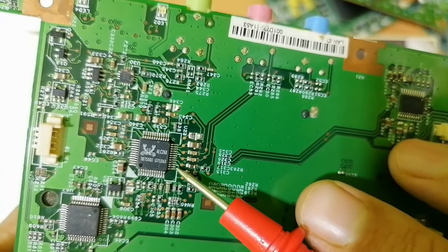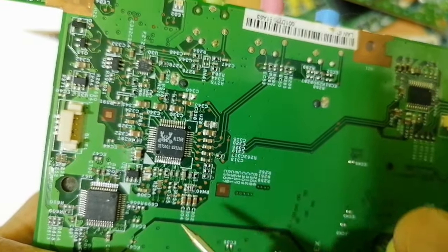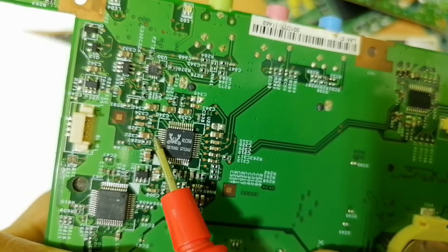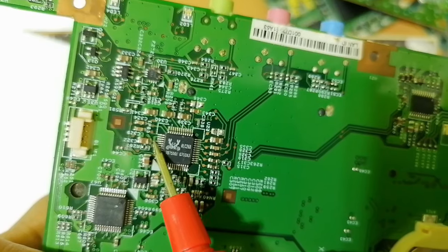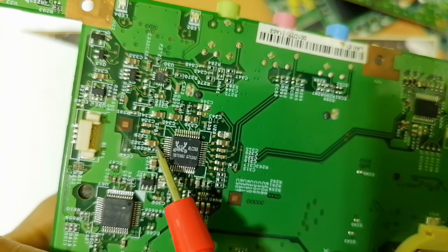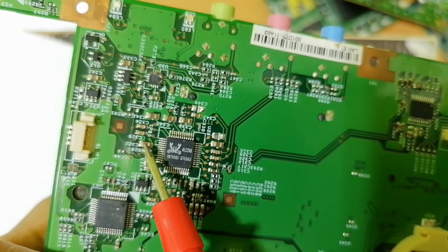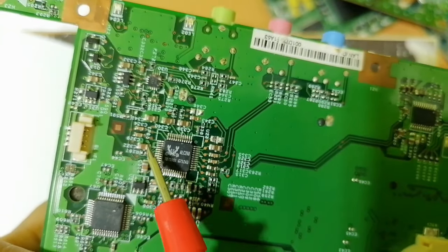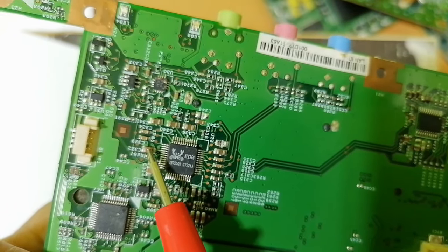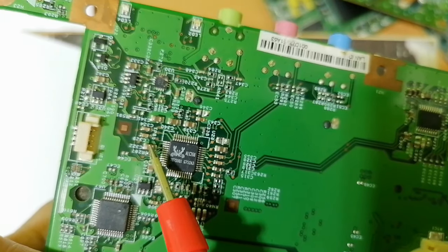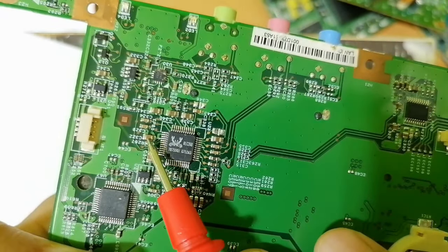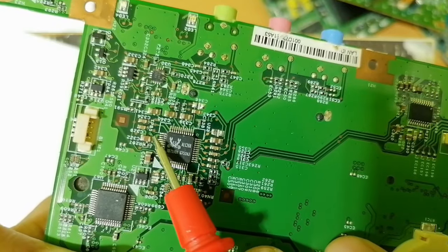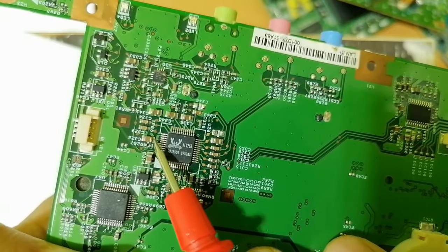That's why, for example, here, let's look for the power where we have the VCC here, as you can see. Do you see the bolded line? This bolded line means we have VCC here. The VCC is connected to this ceramic capacitor. Means if you don't find VCC here, you should check this ceramic capacitor, if it is good or not, because this is the capacitor that feeds this IC with the VCC or the input voltage.